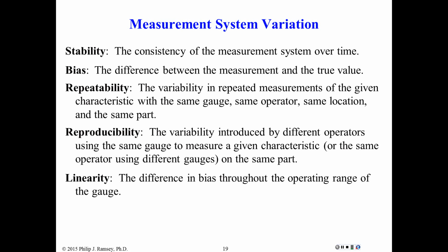So it's not unusual, for instance, in laboratory equipment, they have references or standards, and part of their quality control is to measure those standards periodically to make sure the instrument is stable. That is, the mean response of the instrument is not shifting around.